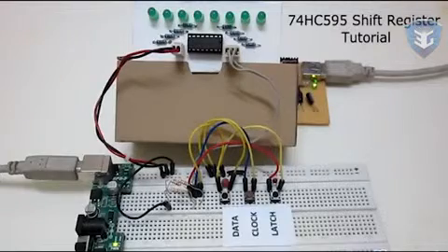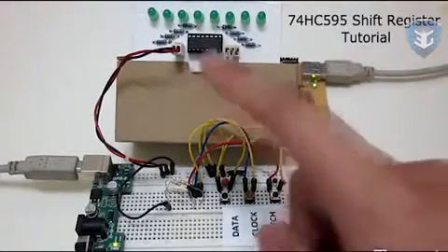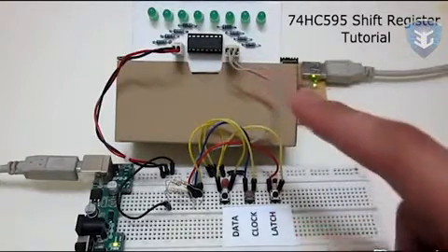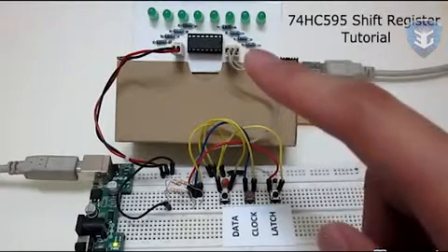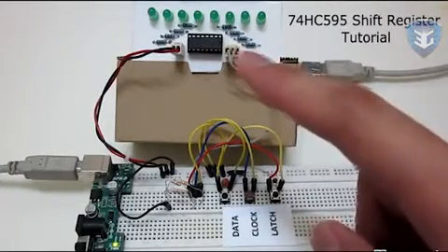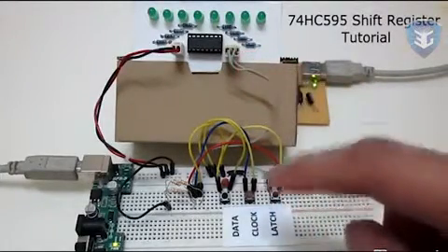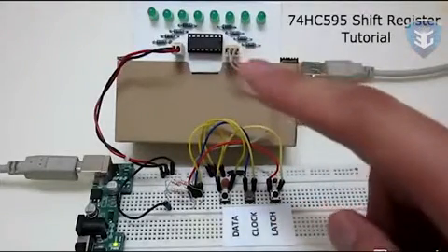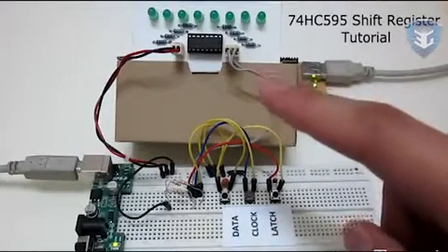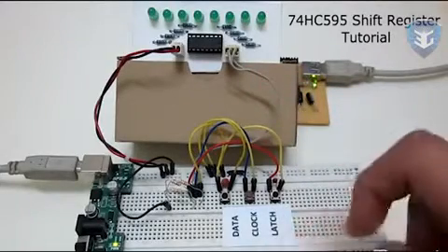After showing the bits shifting in previously, in fact you can send all 8 data bits in and then proceed to press the latch. That means you can change all of the outputs instantaneously, so to speak, with the latch button.